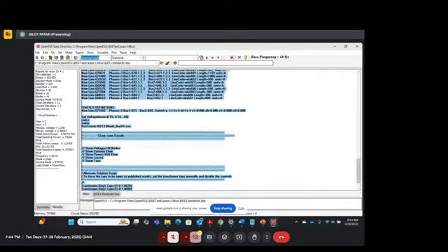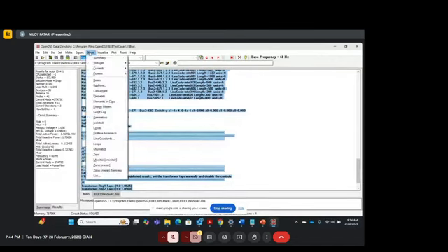It says how much active power is drawn from the substation side, similarly for reactive power, and how much the active losses are. If you want to see even more details, like how the voltages look, go to the Show tab on the top. If you click on Summary, it will show this exact summary that you have.